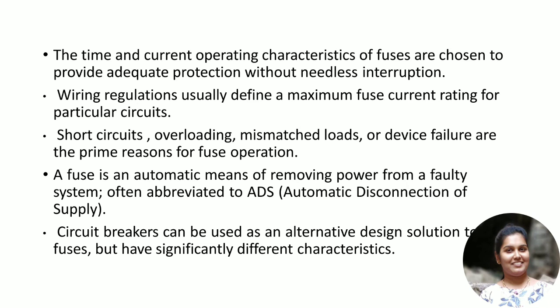And now the fuse we have to use for that particular component should be more than the value that we have calculated. So for example, if the value we have calculated for that particular device is 7.5 or 7.6, then we have to choose a fuse which has a value greater than 7.6 or so. Like we can take a fuse of around 8 amperes or so. So this point should be kept in mind, that is, wire regulations will define the ratings of the fuse.